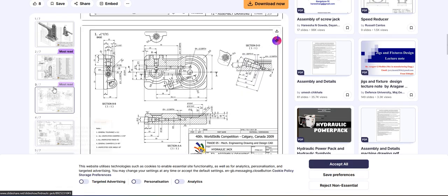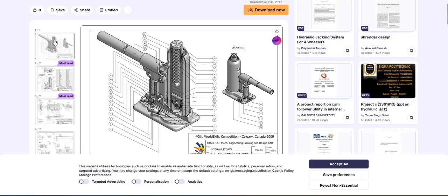Once again, of course, you need to know the work environment and the number of parts required in the market. Usually this will be done by batch manufacturing. You can manufacture something in the range of 1,000 to 10,000 hydraulic jacks per year. The screw is going to be made by machining on the milling machine. Multiple parts are going to be done by the extrusion or the rolling process. The sand cast part for the base will, of course, be machined.